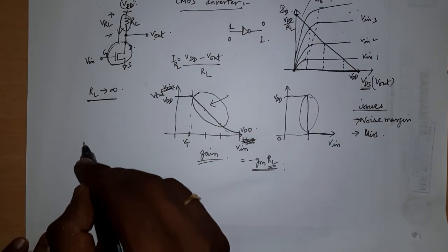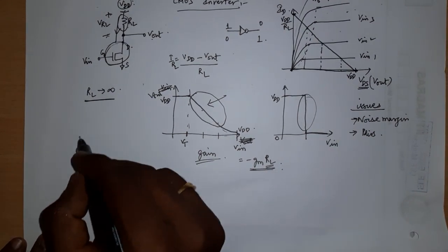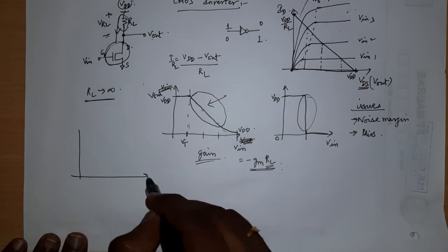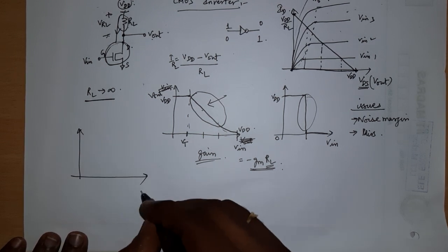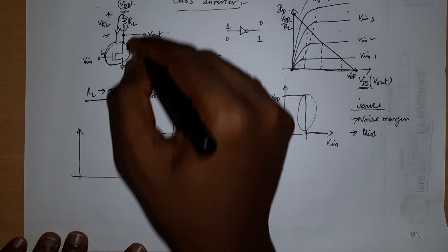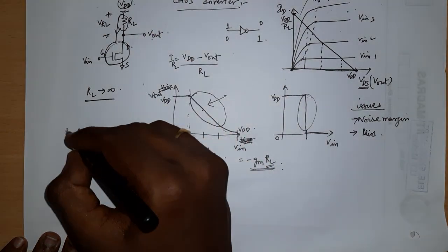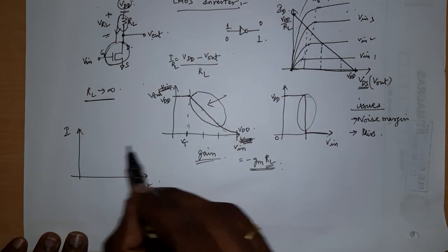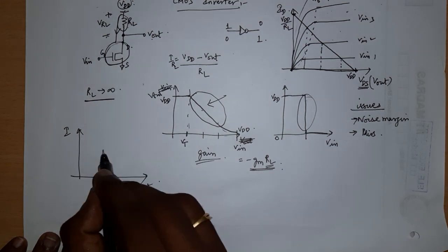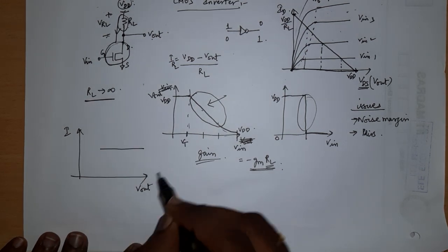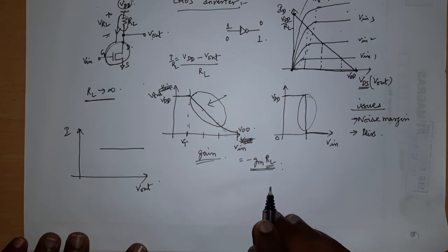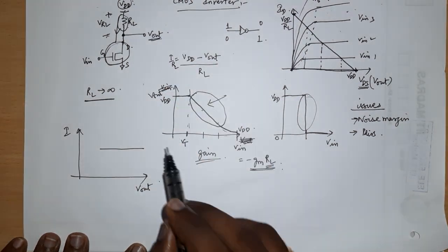Okay, so how to solve this issue? You can graphically try to understand what we just said. When you plot this drain voltage, the output, versus some current, the MOSFET is providing some constant current in saturation region with respect to the drain voltage. Okay, output voltage is the drain voltage.